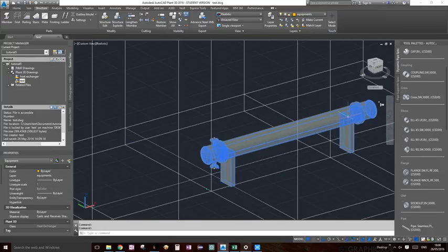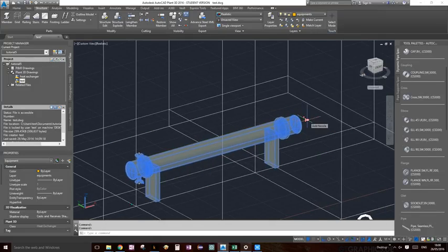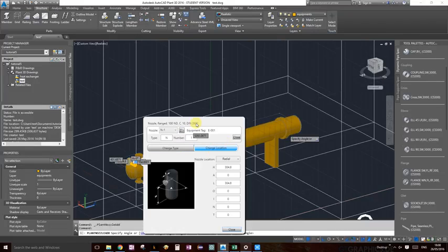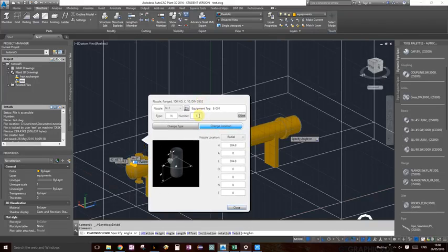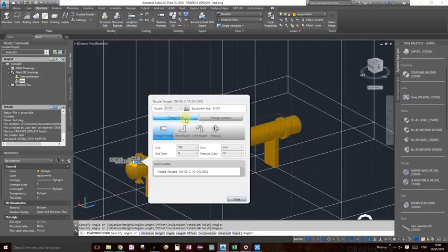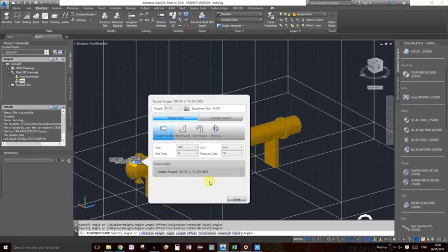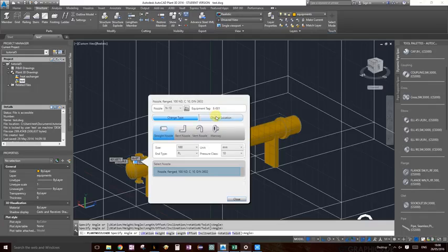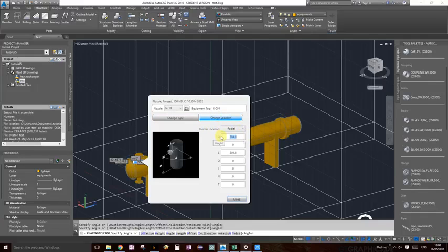Again, select the heat exchanger and let's go ahead and click on that little icon. And this one we'll call 13. And for the tag, let's go to change type again, straight nozzle, and the sizes are all the same. Select the nozzle, go back to change location. Let's choose height 1,000. Might work, might not work, and I'll show you how to change anything if you think it won't work, but usually it will be well defined for you already through the design specs.